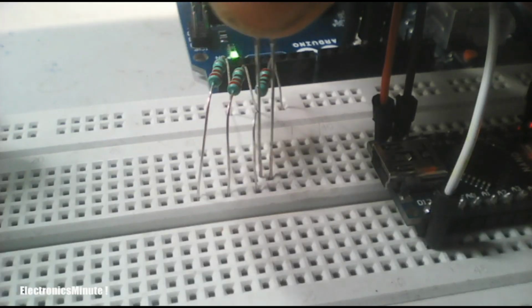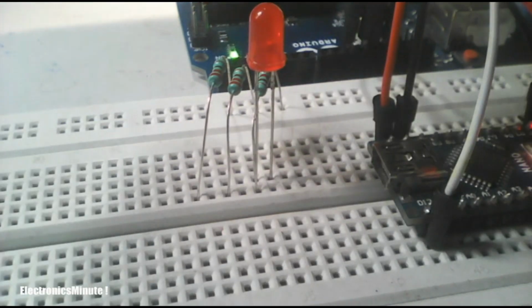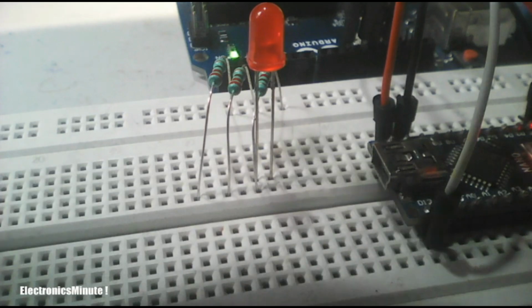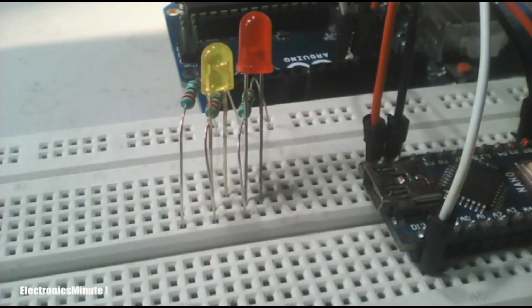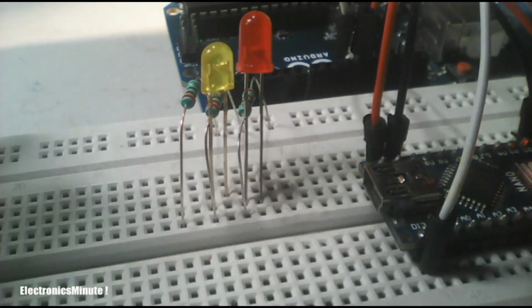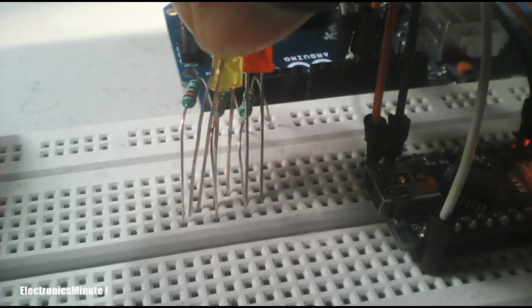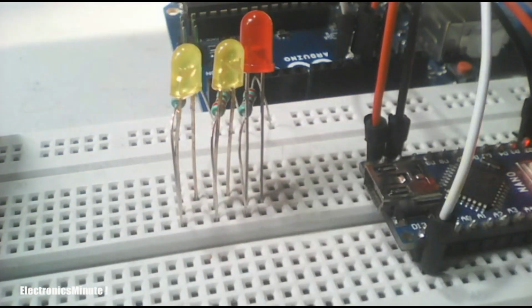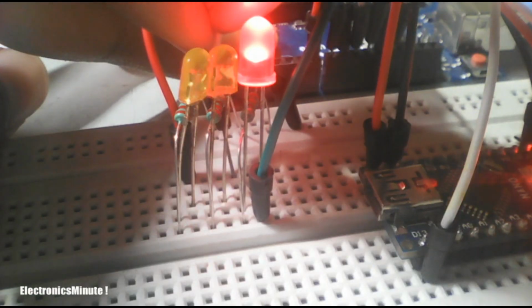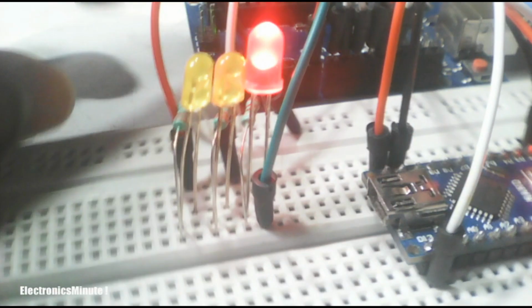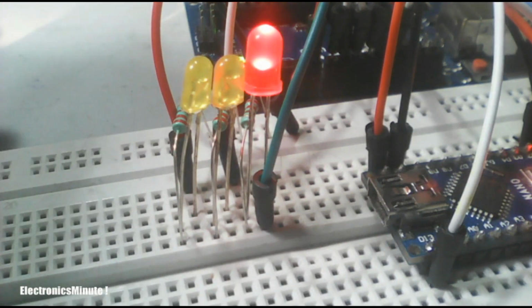Further, you can connect a red LED to pin 8, which will light up when any error arises, and two yellow LEDs to pins 9 and 7, whose job is to indicate that the board is running and that it is communicating with the Nano board. You may skip this lighting effect as it doesn't affect the real task.